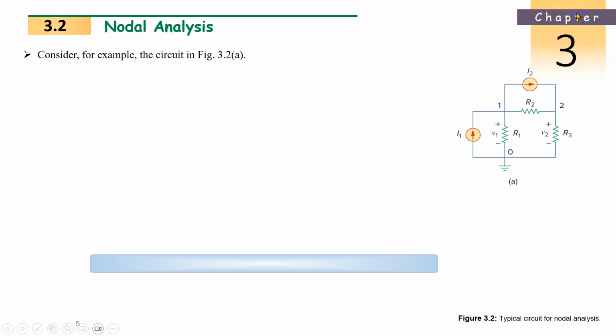But no problem, the steps you followed are correct. If minus comes in the result for I2, then you have to change the direction. I will generally assume left to right, so the current direction is 1 to 2.